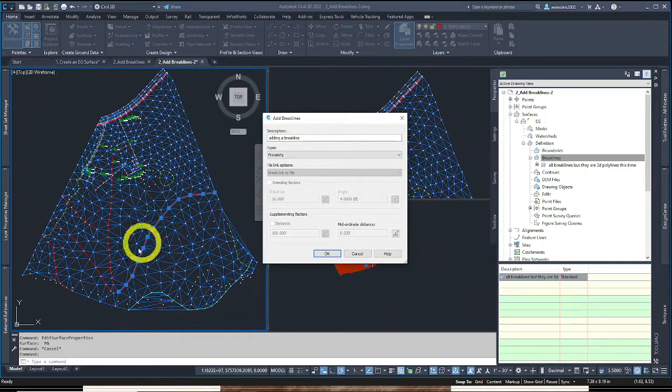So if this was a 2D polyline, it could be used as a break line too, but it needs to take a proximate guess of what the elevations would be by the data around it, and it would force the triangles to break along it. So if you were lacking exact three-dimensional break lines, you could have 2D ones to simulate, let's just say, a ditch or something.